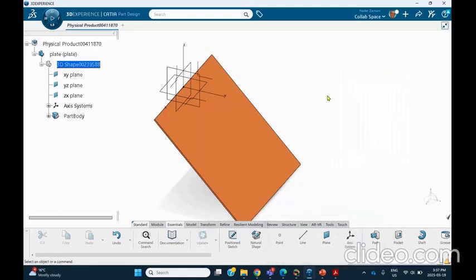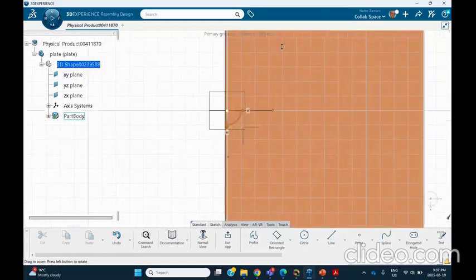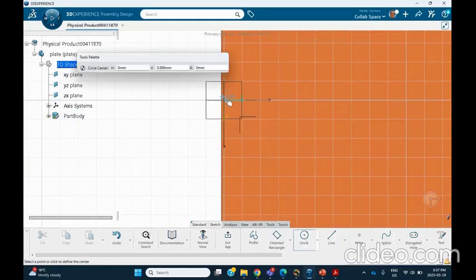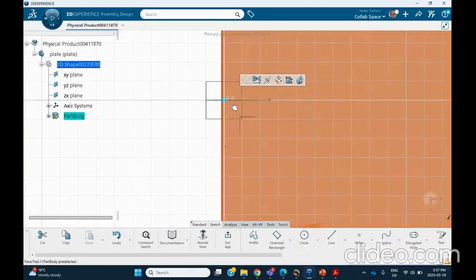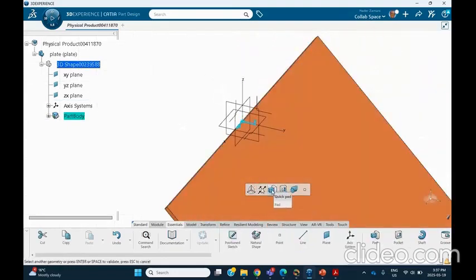Good. All right. Now, on that horizontal plane, I will draw a little circle because I want to make that stand where the revolute is going to be created. So a little circle there. The actual dimension of it doesn't matter. But here, I'll make this thing maybe radius 1. Okay, exit. I'm going to pad this thing up by 10.